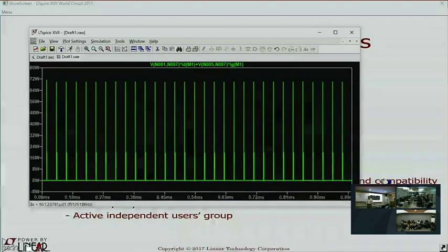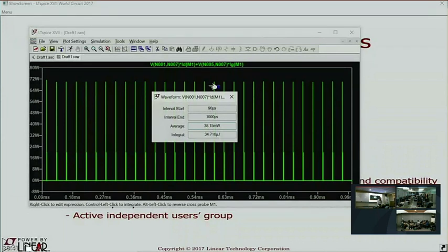But we're in luck, because the waveform viewer can integrate. And to integrate a quantity plotted, you point at the label of the quantity that you wish to integrate with the mouse, hold down the control key, left click, and that will tell you it is 38 milliwatts. And that's the miracle of frequency foldback.